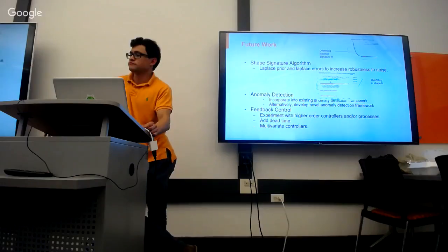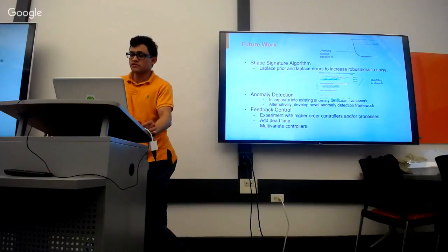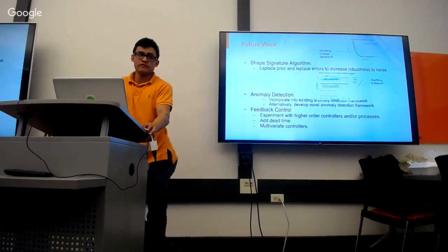Oh, wait, I thought you said you went towards the most complex. Yeah, if there's a tie, go to the most complex, because for me the cost of a false positive is not as expensive as the false negative in this case. Yeah, because you're probably getting amplitudes close to zero anyway. And if you learn a constant model when there are oscillations, you lose a ton of information about how that feedback controller is behaving. So when in doubt, throw in a parameter.